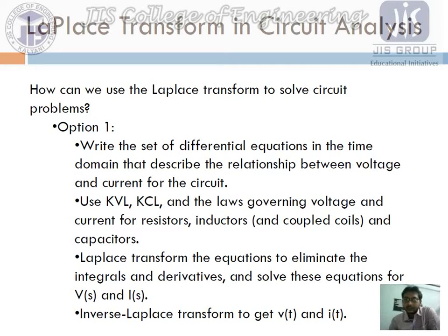If there is an inductor and we want to find the voltage across the inductor, then obviously the L di/dt term will be there. Similarly for the current through the capacitor. For inductor and capacitor there may be some derivative portion, some integration portion. Based on that we write down the equation in the time domain, and then apply KCL and KVL. This is the basics of electrical circuits, and we have already discussed KCL and KVL.